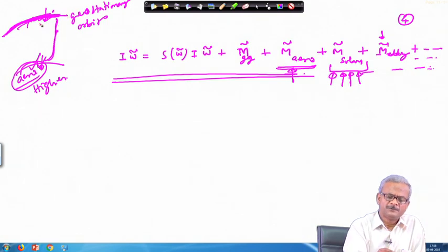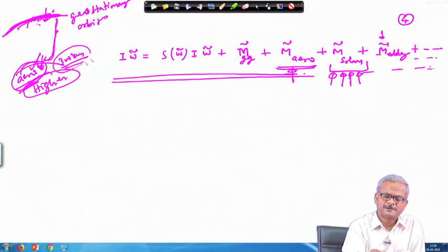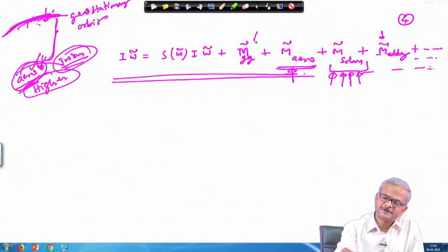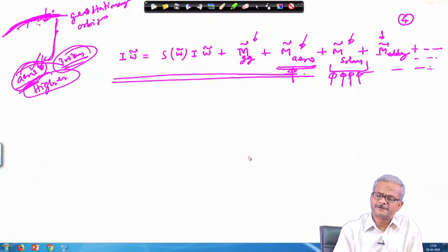You will not get the aerodynamic torque there as you are getting here. It is very strong here in this case, say at 300 kilometer altitude. Your satellite, if you do not correct its orbit, will be pulled down into the earth's atmosphere because of the aerodynamic drag. Similarly, the attitude also gets affected because of the gravity gradient, aerodynamic torque and the solar radiation.